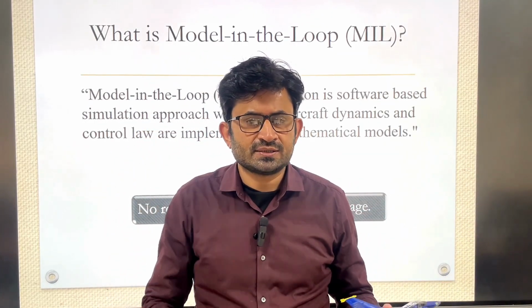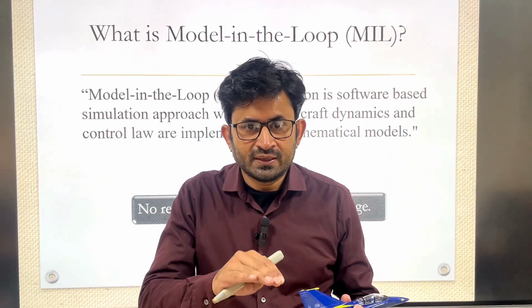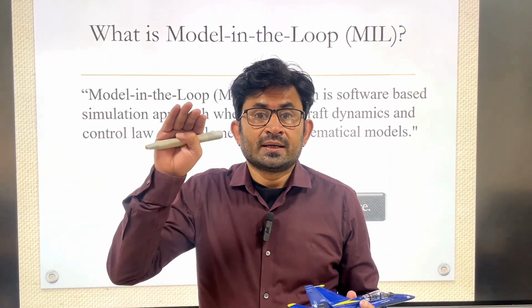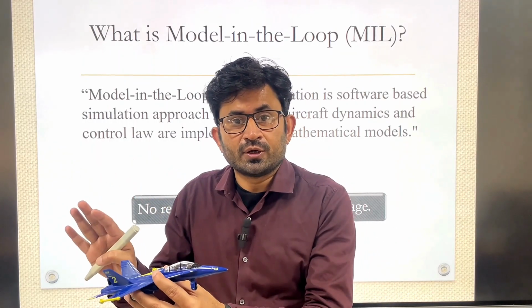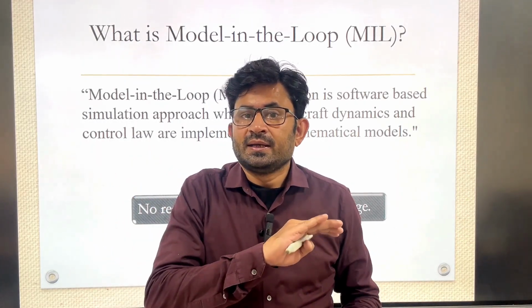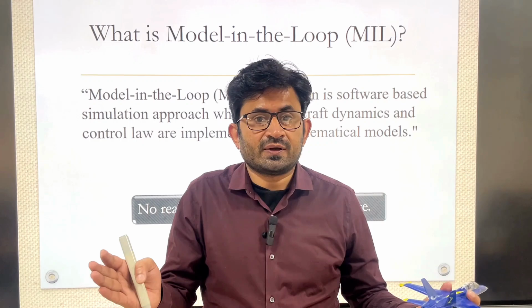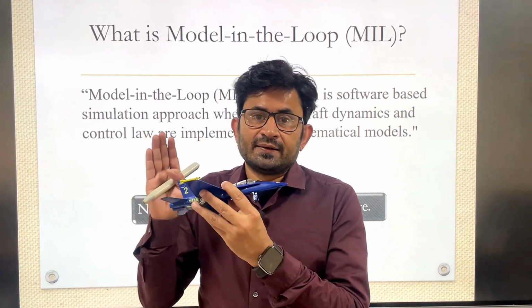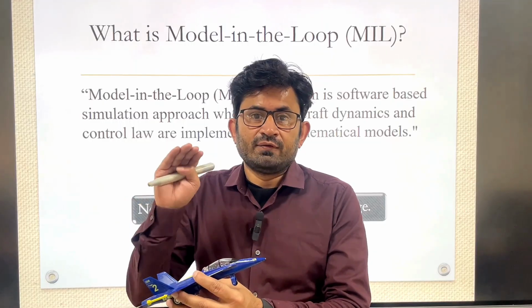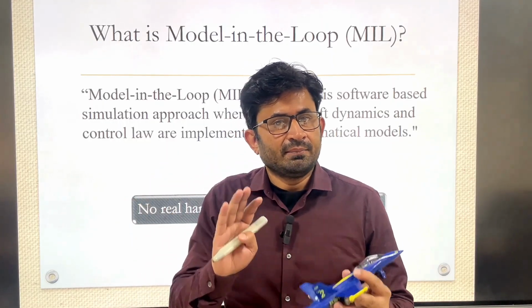In the MIL phase, both aircraft as well as controller will be a mathematical model and will be implemented in any kind of software like MATLAB and Simulink, where both controller and aircraft model will be sitting as a mathematical model.